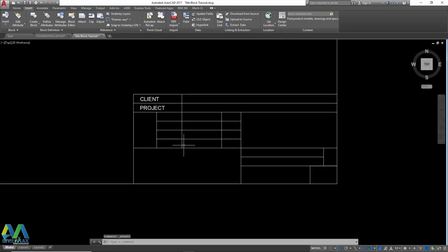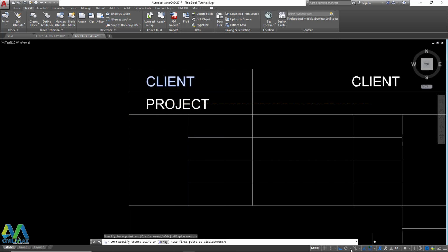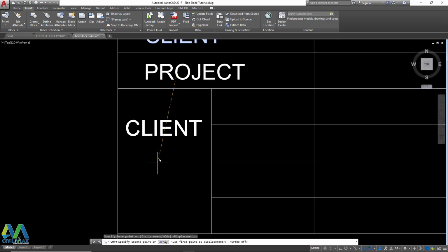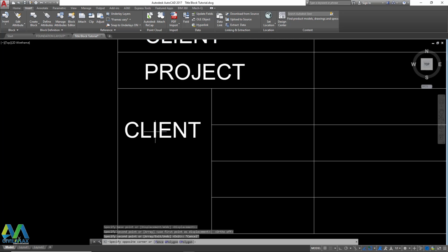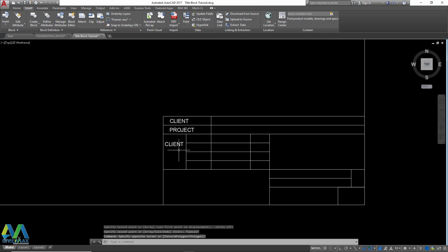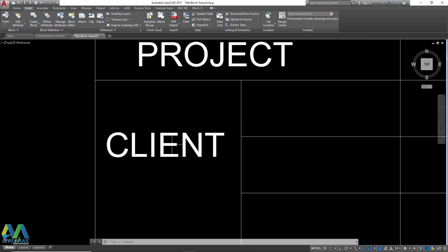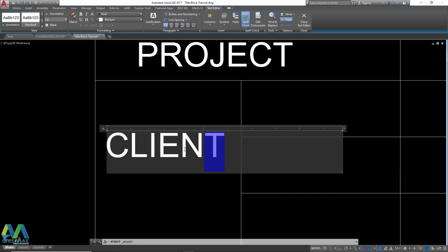I'll leave it right there, and then I'll go to scale right here. Make sure it is in the right position. I'll type there scale. This happens at the moment you've drawn everything the way you want your title block to look, and now we feed in the attributes. Now let me change this text height to maybe 2 or 1.8, right there, 1.8,